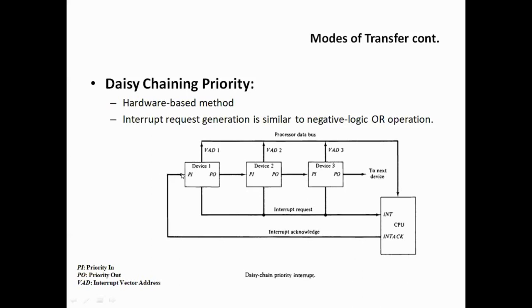Whenever there is 1 here and there is 0 here, it means this device has produced an interrupt and it is also getting an acknowledgement. When there is this combination, this device will start its own routine. That means reading of this device will happen. The reading is done by a routine, a function which will transfer the data from here to here.